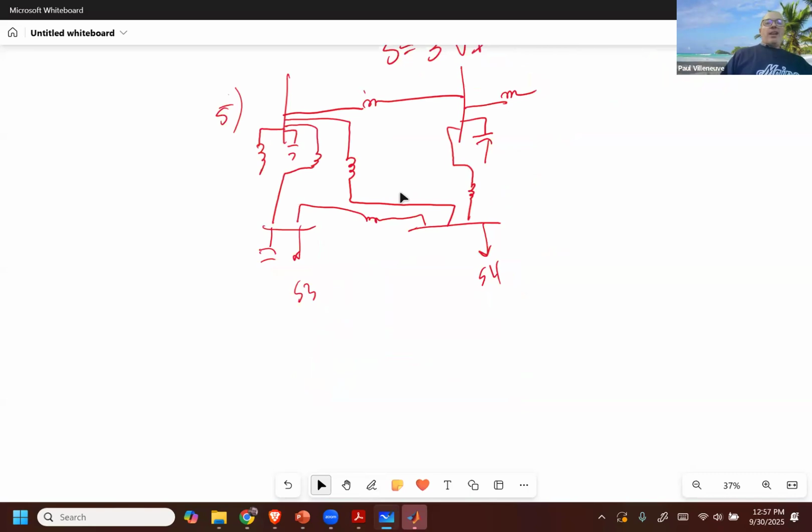Now, the next step you had to do, I gave you these as Z. So let's look at the first one. How did I know that this was a Z? Because does an inductor have a positive or a negative j term? Positive j term, right? For the impedance, for the inductor. So the Y here is 1 over j0.25, which is negative j4.